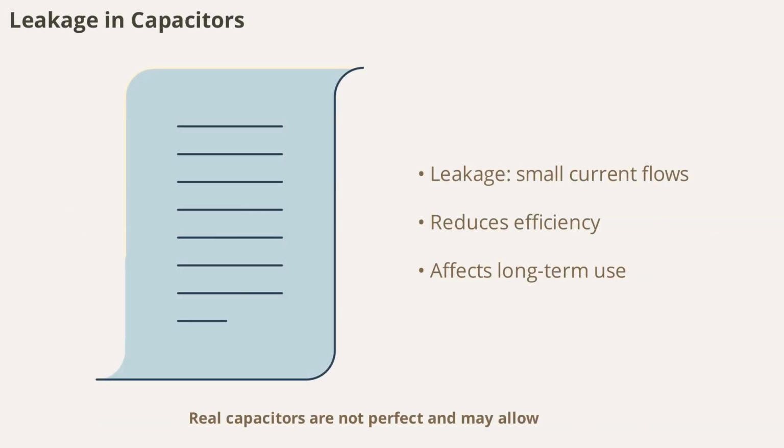Real capacitors are not perfect and may allow a small leakage current to flow through the dielectric. This leakage can reduce the efficiency of energy storage and affect the performance of circuits. Minimizing leakage is important for high-precision and long-term applications.